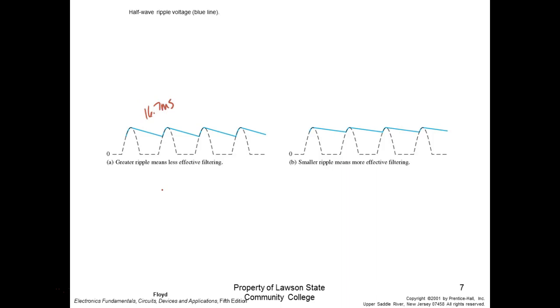You understand that? If it's full wave, which they don't show, then the capacitor's got to run the load for 8.3 milliseconds. So that means on full wave, if I want the same pulse, I could use a smaller capacitor, right? That makes sense? Everybody okay? Y'all know where those times came from? If you don't know, you don't know. Reciprocal of frequency, yeah.